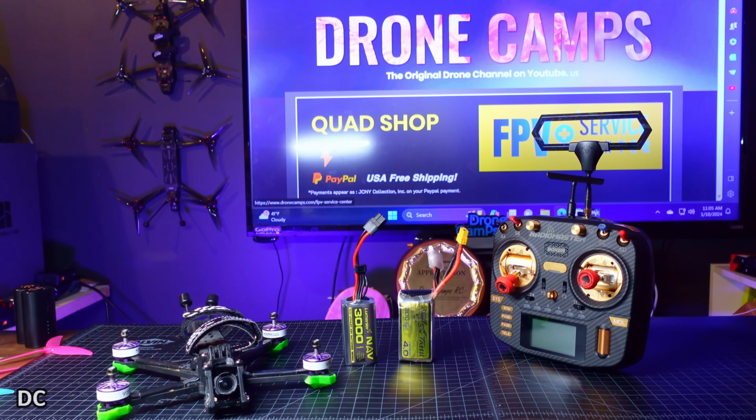Now, the LiPo battery on the right is a 6S 1300 milliamp battery, and most people are flying LiPos for FPV racing and FPV freestyle. The battery on the left, the Li-ion, is mostly for long-range applications: drones, FPV planes and gliders, and FPV wings. That's one of the reasons we fly those batteries: Li-ions need a low amp draw. So if you have a low amp draw setup, a low kV on your motors, not super high kV, then you can fly a Li-ion on it.